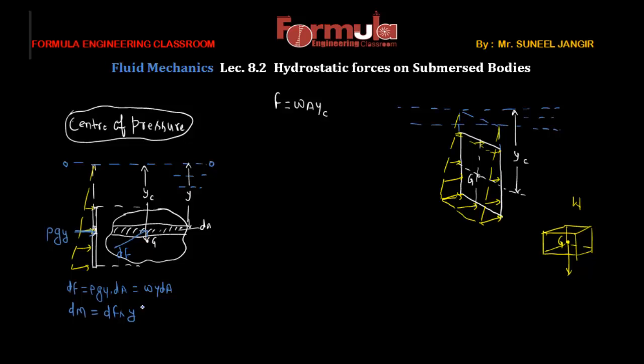So this is the elementary moment created by this elementary force about the free surface. So we can also write this one. So force is W y, there is also y here, so y square dA. Okay, so this is the elementary moment.